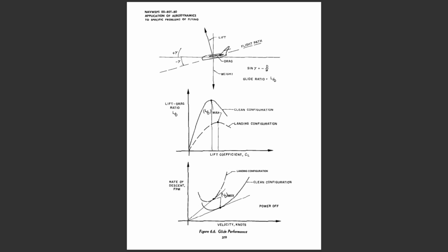When a straight line is drawn from the origin tangent to the curve, a point is located which produces the maximum proportion of velocity to rate of descent. Obviously, this condition provides maximum glide ratio. Since the rate of descent is proportional to the power required, the points of tangency define the aerodynamic condition of L/D max. Factors affecting glide.